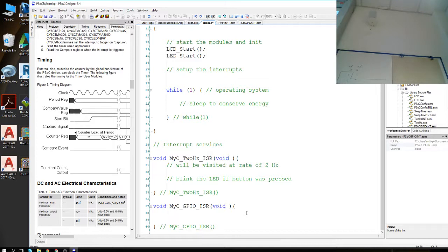Basically, this routine just sets a flag: now I have been pressed, do something. And that's actually the correct way of using these interrupt service routines in any case. Do as little as possible in those interrupt service routines. If there are, say, calculations which take time, usually any arithmetic operation will take more time than simple operations. Then you would just have here the flags telling the other parts of the program, okay, go on and do whatever has to be done.